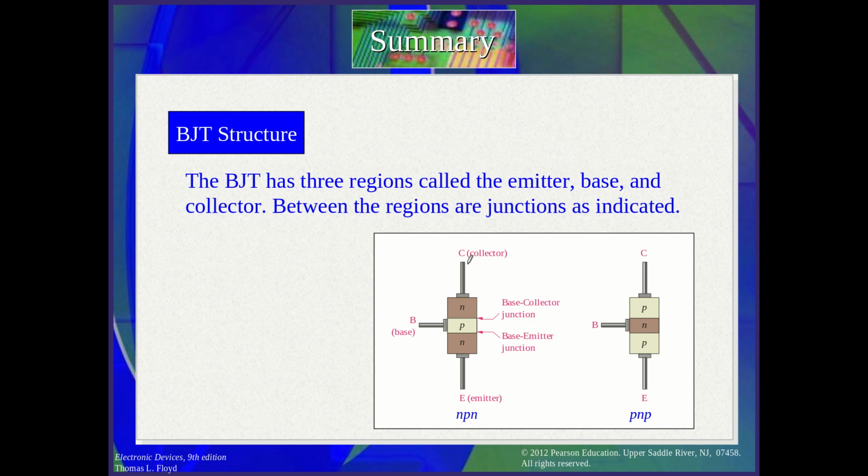Okay, now let's see something else. The data sheet. Yes, the data sheet is very important because it is given by the manufacturer of the transistor that you have, the BJT transistor, and it gives you all the information that you need to work in the normal condition, the condition that your transistor can work in. It gives you the beta, which is given as HFE.